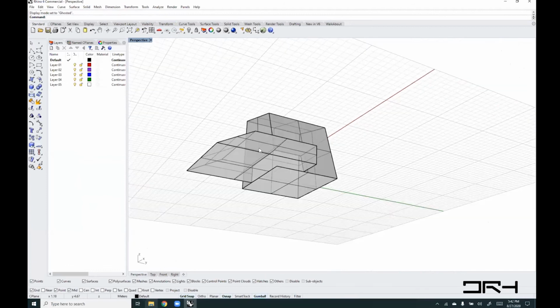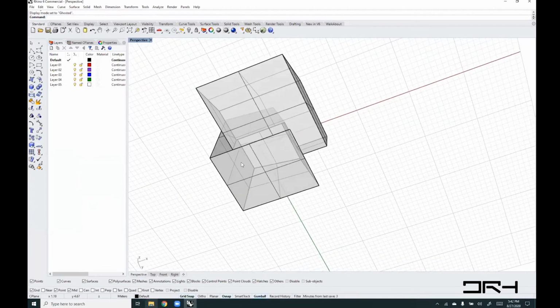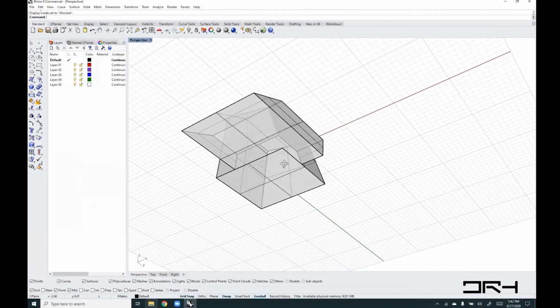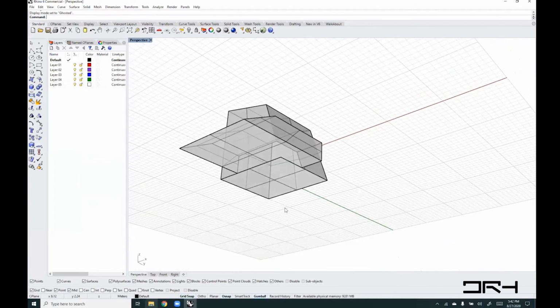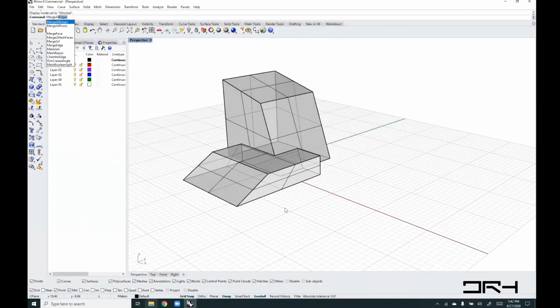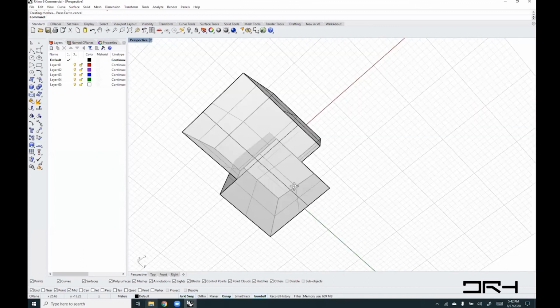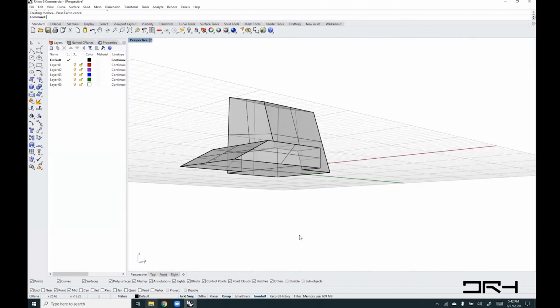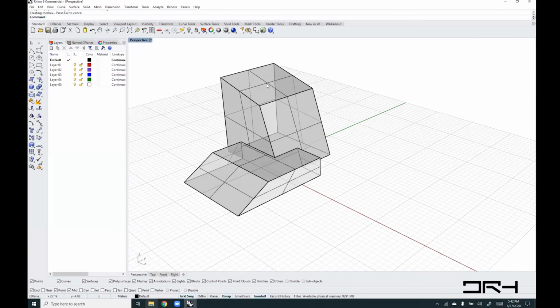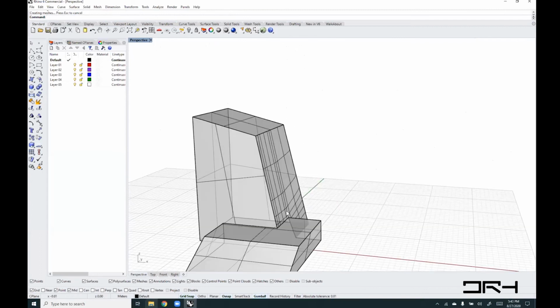However, you see how the base now has 2 faces coincident or coplanar to each other. You can clean things up by using merge all faces, and all coplanar faces are going to be merged into one surface in this case, right? I can continue to sub-object select and edit. And in this case, okay, you see what happened here.